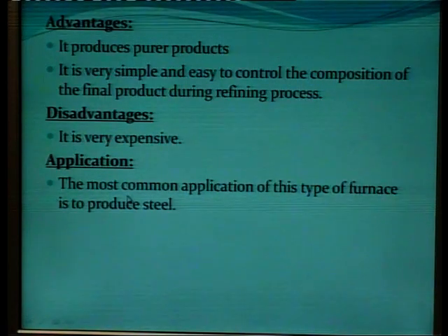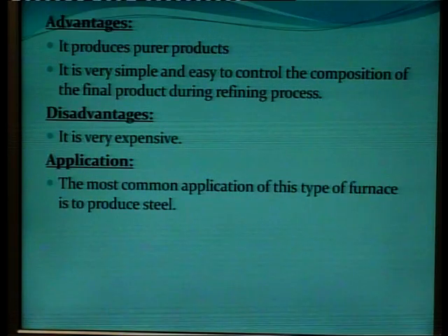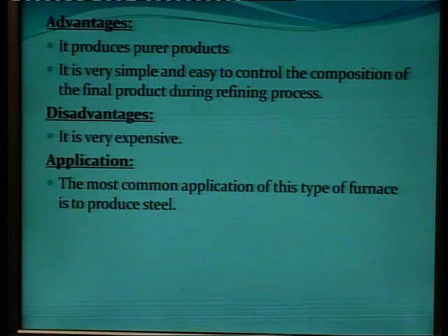Now advantage, it produces purer products. It is very simple and easy to control the composition of the final product during the refining process. Disadvantage, it is very expensive. And the application, the most common application of this type of furnace, is to produce steel.